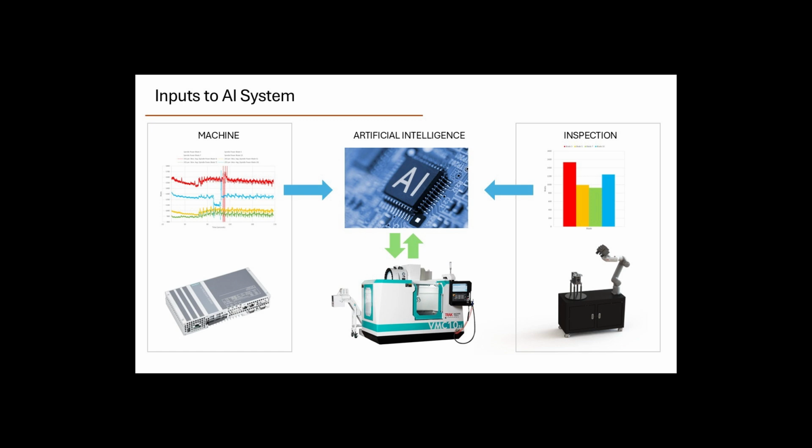And then we have post-inspection, right? So once the parts are produced, we want to put them on inspection equipment that can provide digital information. Those control points that I showed you before, on the 3D scanner, we can scan the entire surface, align it to the CAD based off the datums, and then extract the deviations of those control points, as you saw in the inspection setup. Those deviations then go up into the machine learning solution.